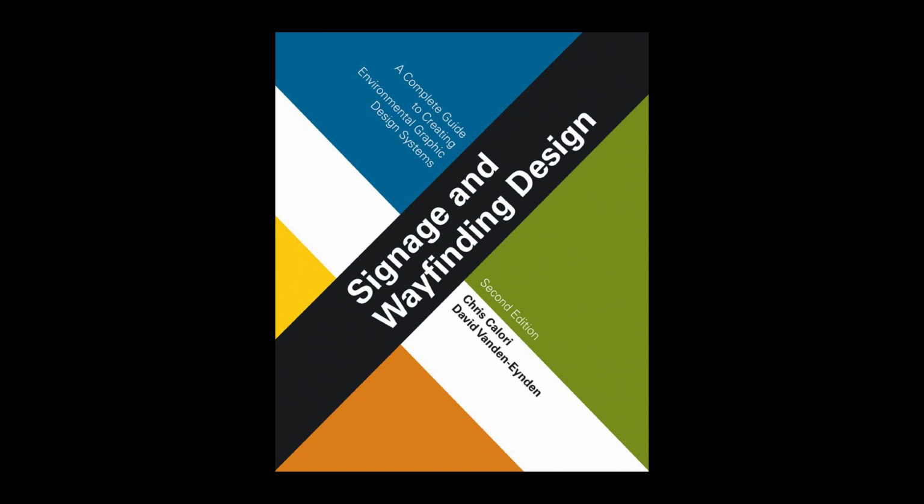For example, several elevations may be required to show the different mounting conditions for a given sign type at different locations, but a typical mounting elevation can be used for a condition that's the same at many locations, such as wall plaques mounted next to doors. At this point, the drawing number for the mounting elevation corresponding to each sign number is entered into the message schedule.